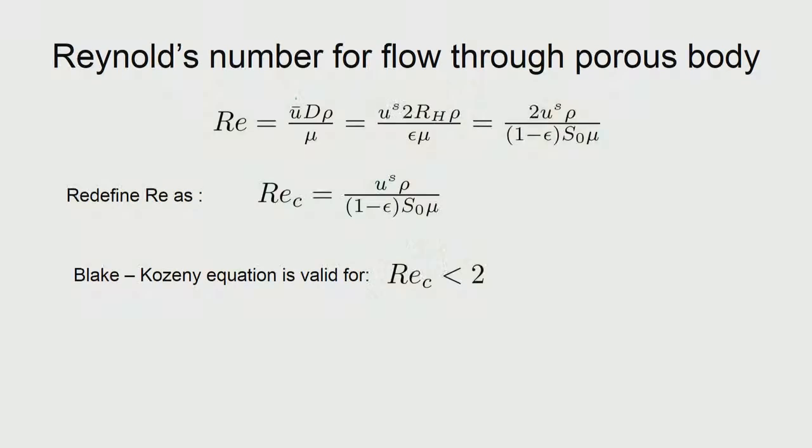The way to validate is the same as for the pipe flow. So, look at the Reynolds number and check whether the Reynolds number is within some range or not. The porous medium has been modeled with these quantities being a bit different. The u is basically the superficial velocity, and here the Reynolds number should have the actual velocity. So, we must substitute properly. The diameter is basically twice the hydraulic radius, so we must also bring in the hydraulic radius expression. So, we bring that in and we see that the Reynolds number will come out to be an expression like this.